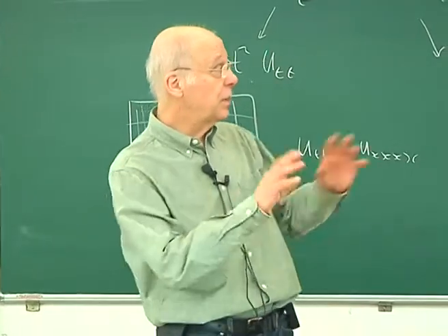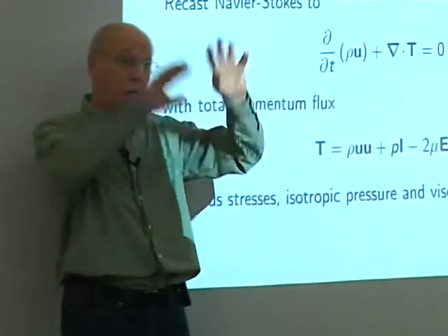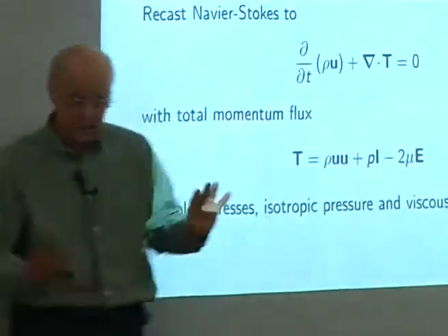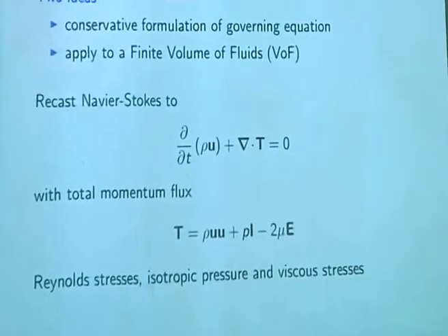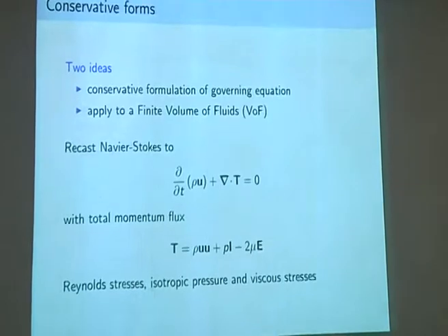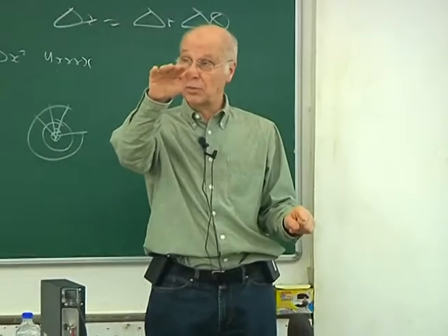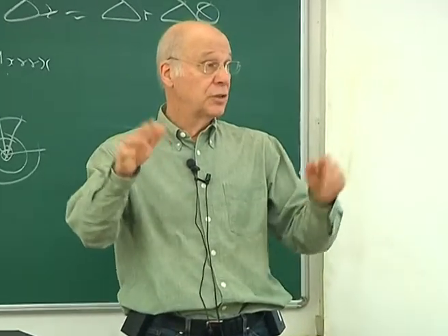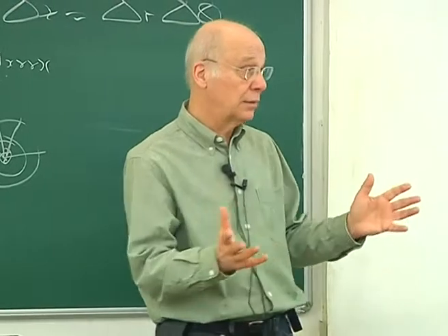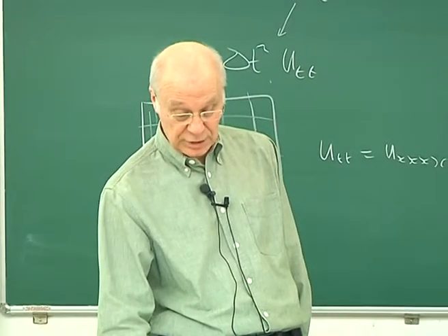And then if I were to integrate this equation over the whole domain, in the steady state, so in the steady state there's no time derivative, if we integrate that globally, we would get the integral of the stress around the boundary, which is exactly the force on the top has to be equal to minus the forces on the sides and the bottom. So it would be exactly right. So that's the conservative form of the differential equation.